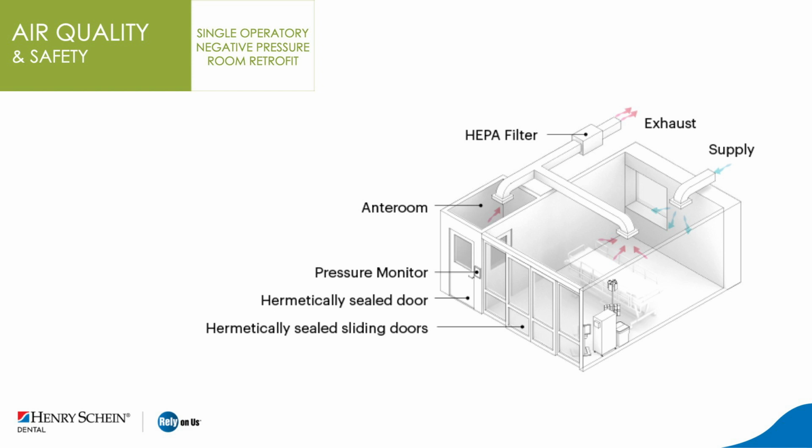And outside air can be introduced into the heating and air conditioning system by adjusting the outside air dampers on the air handling unit, either mechanically or electronically. Okay? So we don't have to make this decision ahead of time. We can actually adjust it during use.